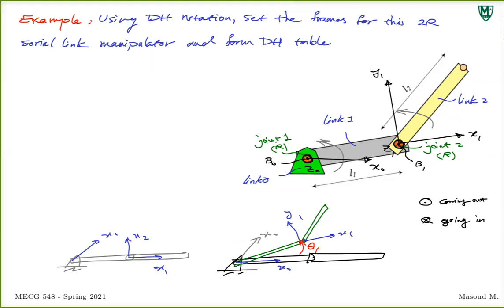Once you know x0, well, right hand rule: four fingers show the direction of z0, make a fist, from z0 to x0 your thumb shows the y-axis. Y is not really the point of interest, because once you know x and z, that cross product tells you the direction of y.